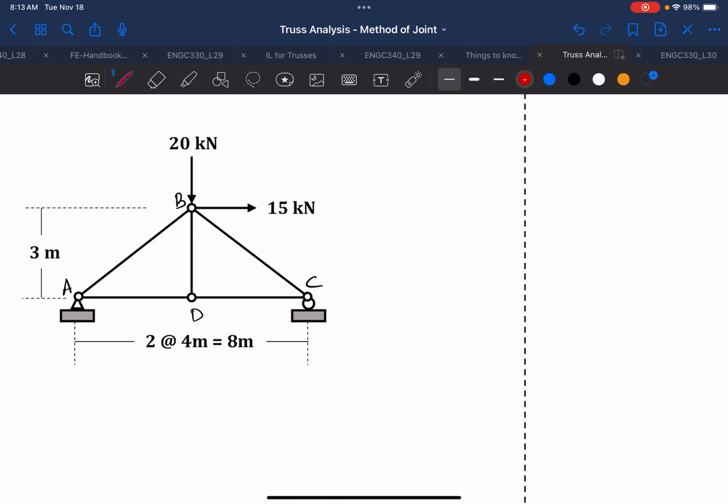When analyzing the truss, generally we go for finding the determinacy, but since the question is already asking for an actual member, we don't have to show that it is determinate. By default we assume that it is a determinate structure, which means that using only equilibrium equations we can solve all the forces. So we'll find all the lengths.